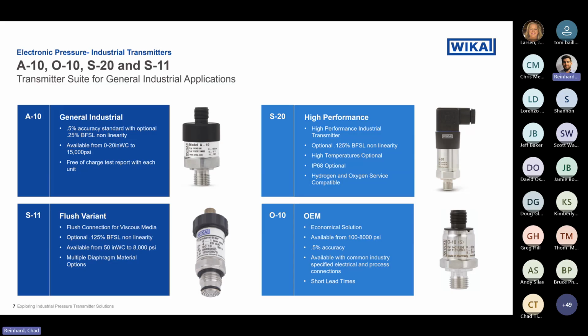S11, again, S20, basically with a flush seal. You can also get an integrated cooling element built onto this. So that would get you up to 302 Fahrenheit. Generally speaking, things like food and bev, et cetera, we do have FDA requirements. So we have FDA 21 CFR if you're in any of those applications. But again, really this is just meant to be a flush seal, so a little bit of a protective barrier in the event that the application calls for it.